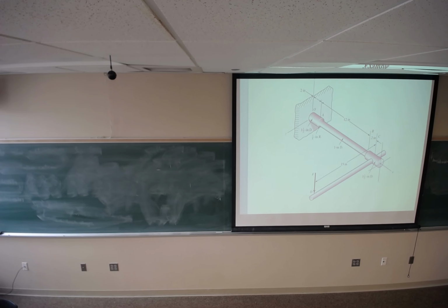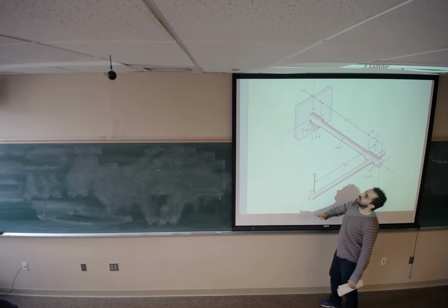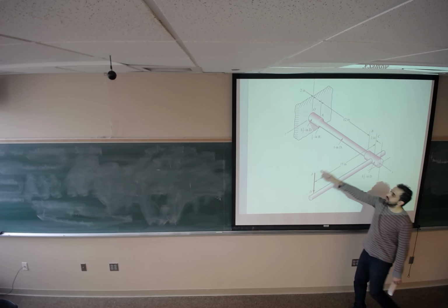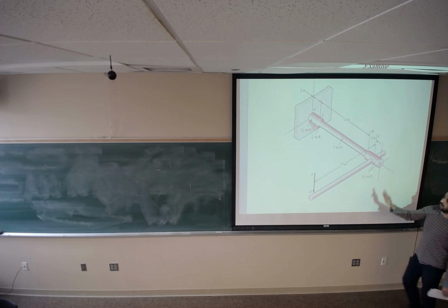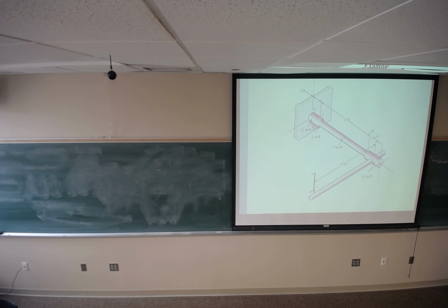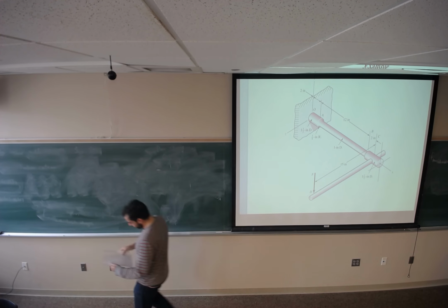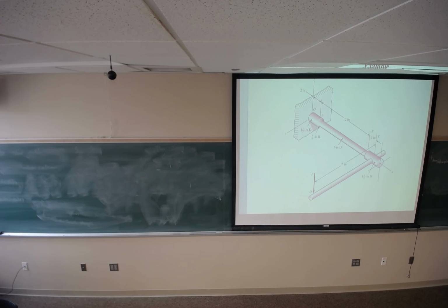We should check both because one section, which is here, is going to see the smaller diameter, which provides the larger stress. The other point is going to see the larger moment and torque applied to that section. We should check which section is going to see the greater stress. Does it make sense? So there are two possibilities.